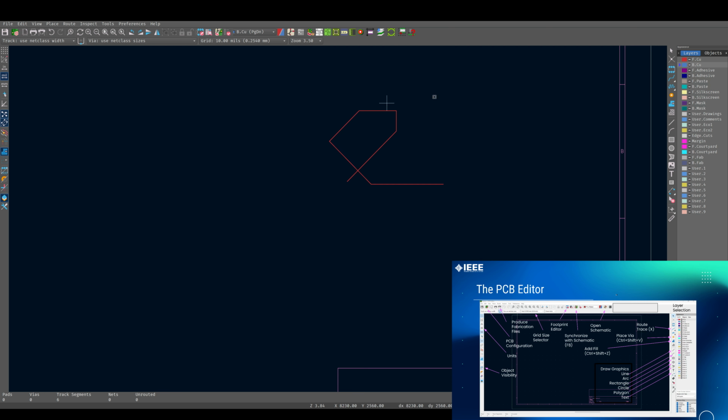Add a track, adds a wire as I did before. So a track, yeah, see. And then we have add tune track. You don't need to worry about that. It's a little more advanced. Add a via right here. Vias are basically holes that go through the board to connect one or more layers. I went over this in the beginning, but it's just a quick refresher.